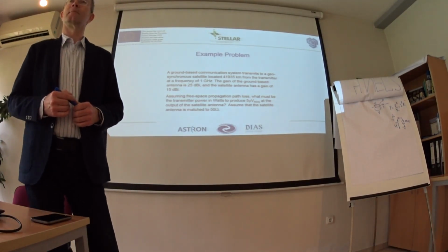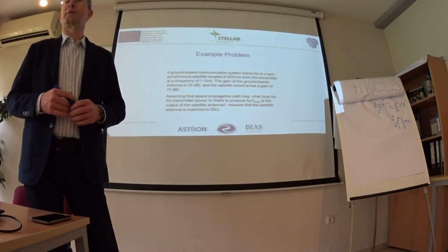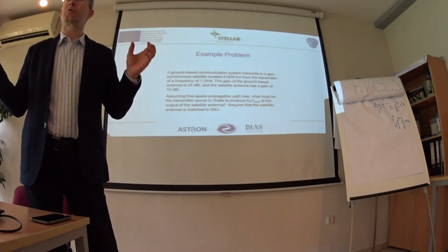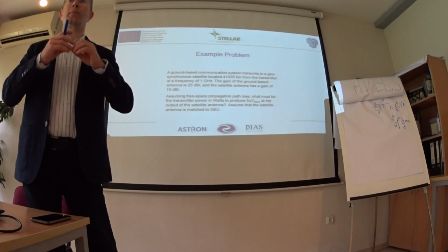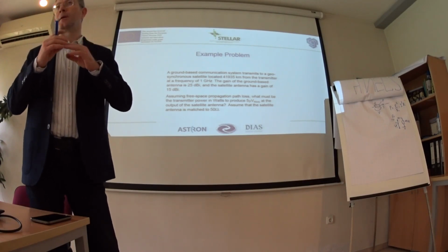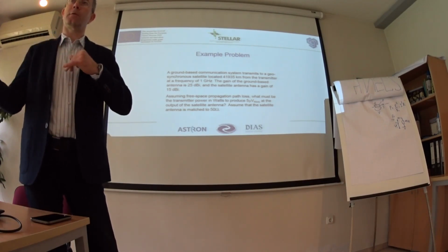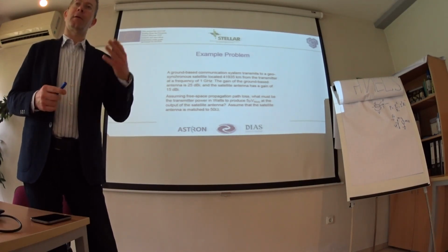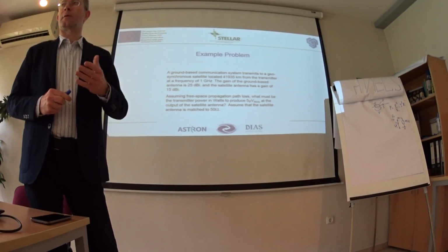Is the resistance 50 ohm? Yes. This is the standard impedance of any instrumentation. 99% of them are made to have an input impedance of 50 ohms for many reasons. The other standard is 75 ohm, the other standard is 100.